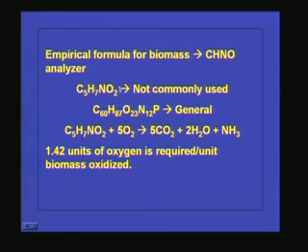If you take the simple formula for the microbial cell, C5H7NO2, and want to find out the total oxygen required for the oxidation of this cell, because we have incorporated this oxygen requirement in the initial formula, that means Q into BOD of the influent minus BOD of the effluent. If we can find out the oxygen required for the complete oxidation of this, we can deduct that much from the initial value, and then we will get the total oxygen requirement in the system. So, to find the total oxygen required for the complete oxidation, what do we have to do?